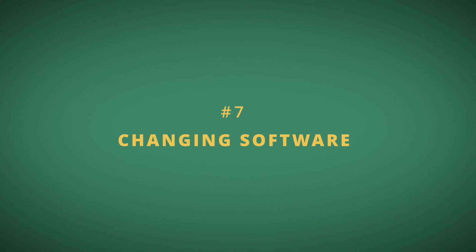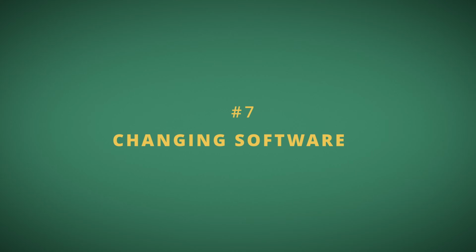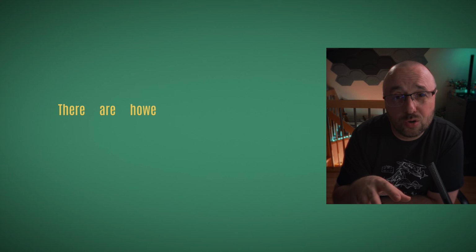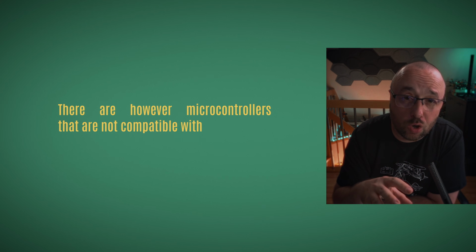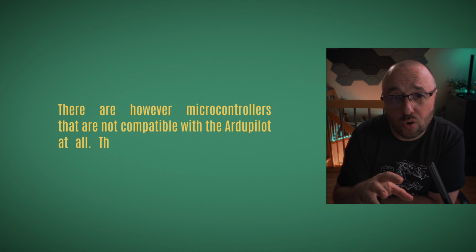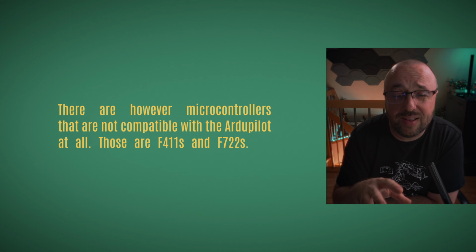And the funny thing is that usually the hardware is compatible with all three of them. In most of the cases, if the flight controller works with INAV, it also works with Ardupilot and Betaflight. If it works with Betaflight, then usually it also works with INAV and might work with Ardupilot. There are, however, microcontrollers that are not compatible with Ardupilot at all. Those are F411s and F722s.